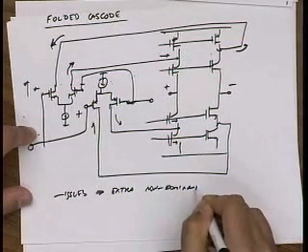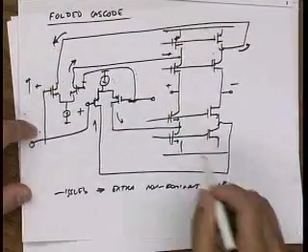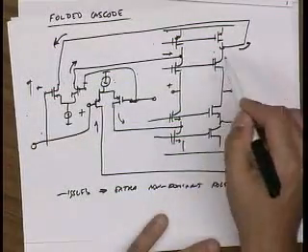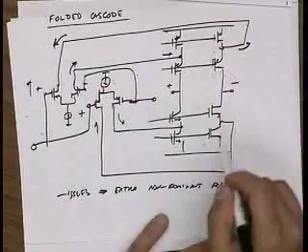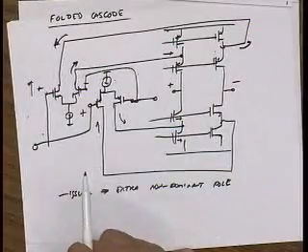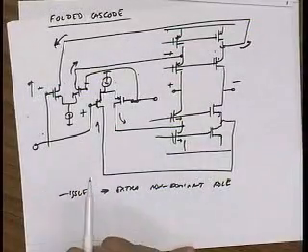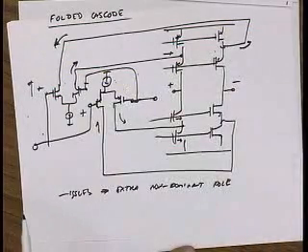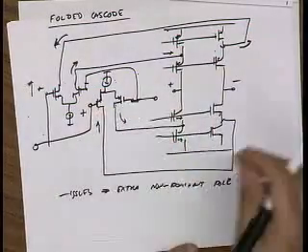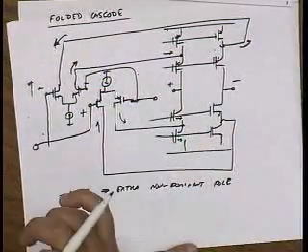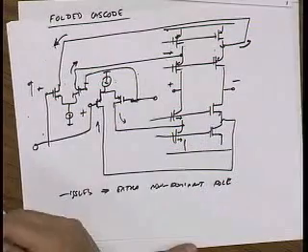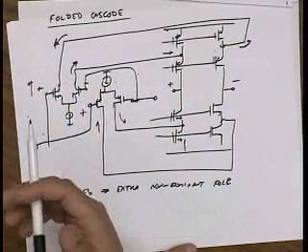And of course, you can size things appropriately, right? So you can size things so that, let's say I get my non-dominant pole from my NMOS devices. And to start out with, my NMOS devices are roughly a factor of 2 faster. And then I can size them so they're a factor of 4 or 5, so that this sets the non-dominant pole. So if I'm going for pure speed, just trying to get the most speed possible, you're right, you're limited by the fact that you have 2 non-dominant poles. But usually you're not designing for pure speed, right? You're designing to meet specs. And transistors these days are so fast that you have a lot of flexibility when it comes to speed.